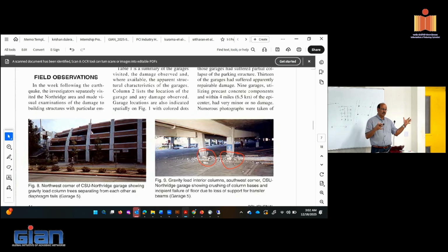So when they go for the ride, these end regions are supposed to be pin-ended. They're not fully pinned. I mean, they don't put a pin through there. They do put, so they basically bring steel plate connections. They reduce the section dimension and then run a rod through. So that system will resist some movement. And if it doesn't go for the ride, you will start causing some damage in that region as well. Theoretically, they are pin connections.